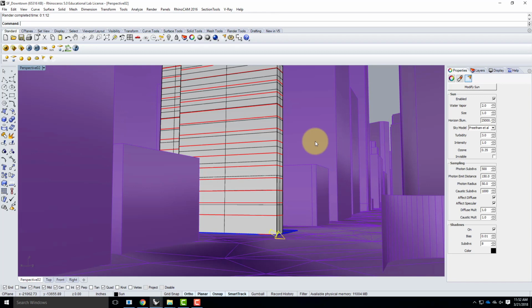The problem with this is it's a destructive thing to do. You're destroying the model, the background San Francisco city, and replacing it with this proxy object, and you can't go back once you've created it. So it's a one-way deal. It can be beneficial for rendering and for working in your Rhino file, but not all the time. It doesn't make the rendering faster, it makes working in Rhino faster.